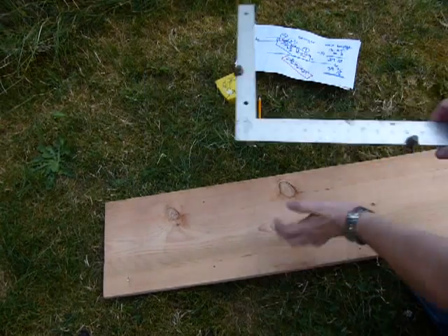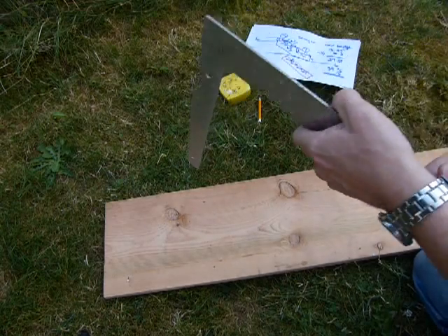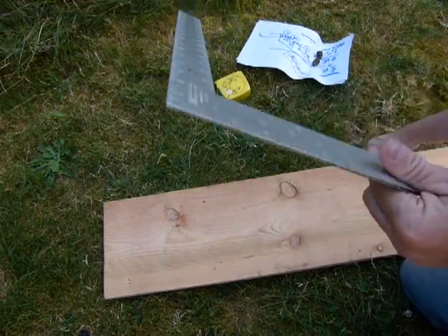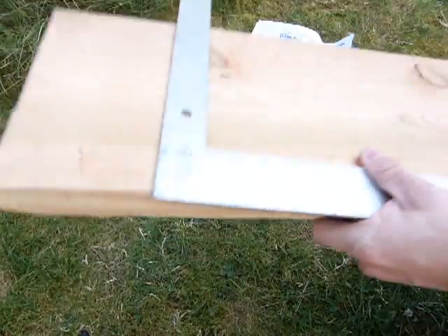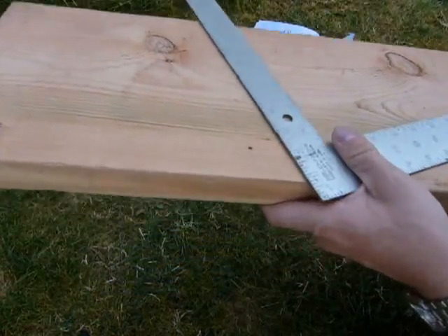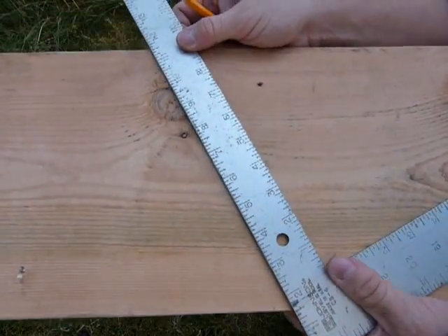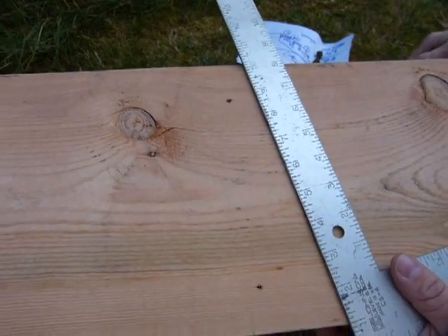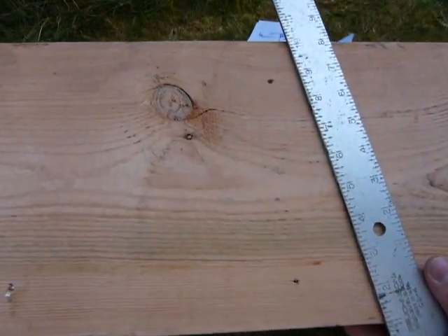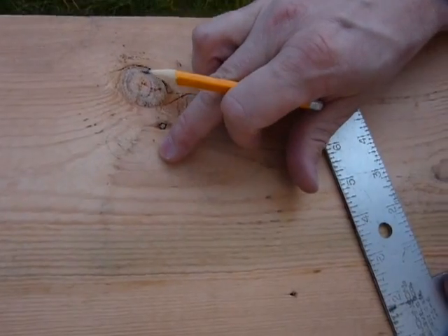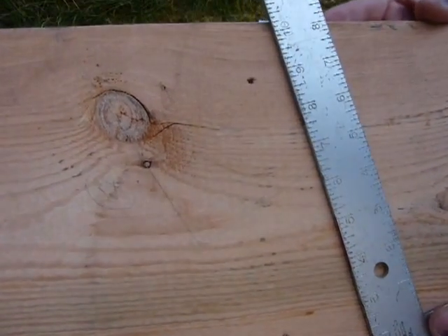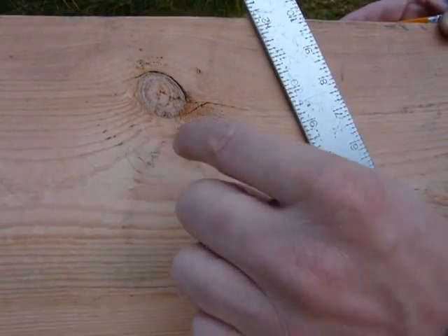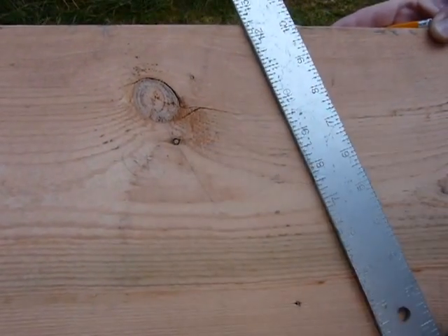To get my plumb cut and level cut, I'm gonna need to get the stair gauges off, and this is how it is done. That's my 4th riser, but that 4th riser is not going to be a problem. It's not going to be in the way. Can you guys see that number 4? So that's my 4th riser. That knot actually is not going to be in the way, and this 4th riser is going to be formed by the edge of the landing.